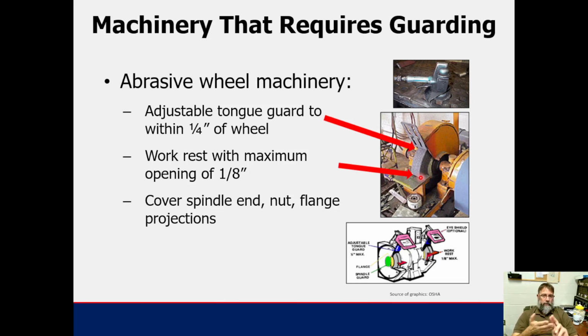OSHA requirements state that there needs to be a maximum opening between the wheel and this rest right here of 1/8 of an inch, maximum 1/8 of an inch. And then up top is the tongue guard, maximum 1/4 inch to the wheel. So if you ever see any of those things that are out of spec, then you're going to need to adjust. This rest will slide in and this tongue guard will slide down.